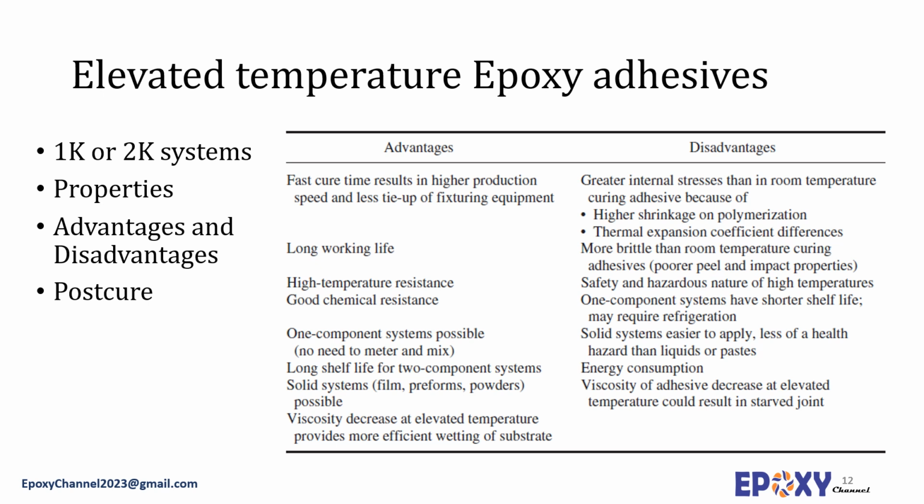Elevated temperature curing epoxy adhesives are often given a post-cure. Actually, in the curing process, the system is first cured to a state in which the bond is capable of handling, where the fixturing used to hold the parts is released, and the bonded component goes to the next manufacturing stage. After reaching the handling strength, the joint is post-cured by applying heat until it achieves full strength.